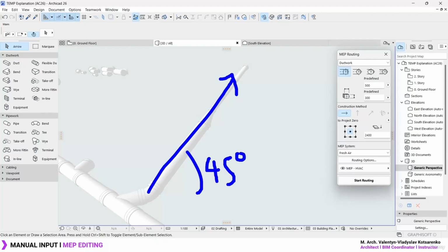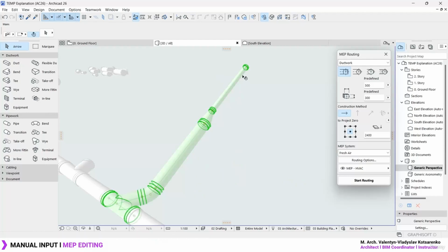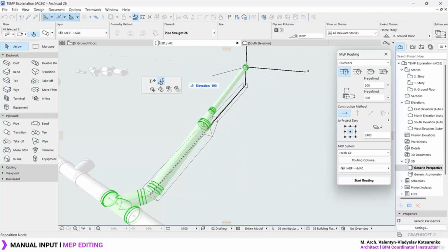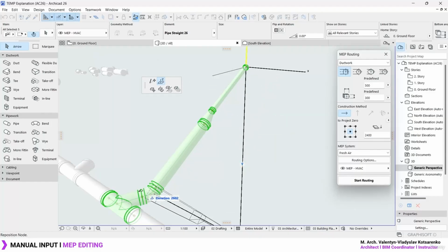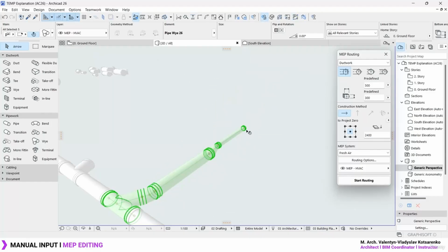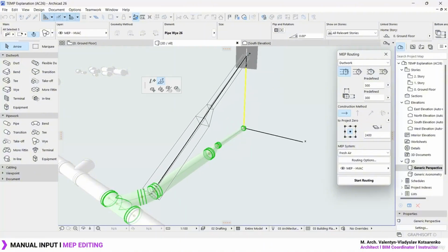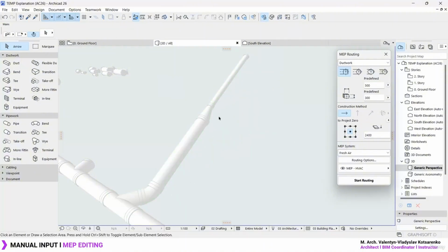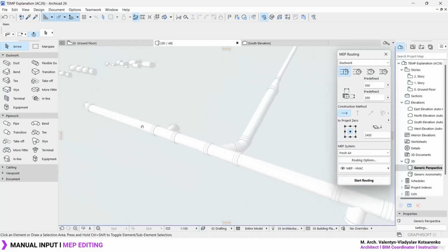You can start positioning everything at a horizontal displacement, and then simply activate the move or elevate node command, which will allow you to create sloped or vertical types of branches, which is quite an amazing command to have into consideration.